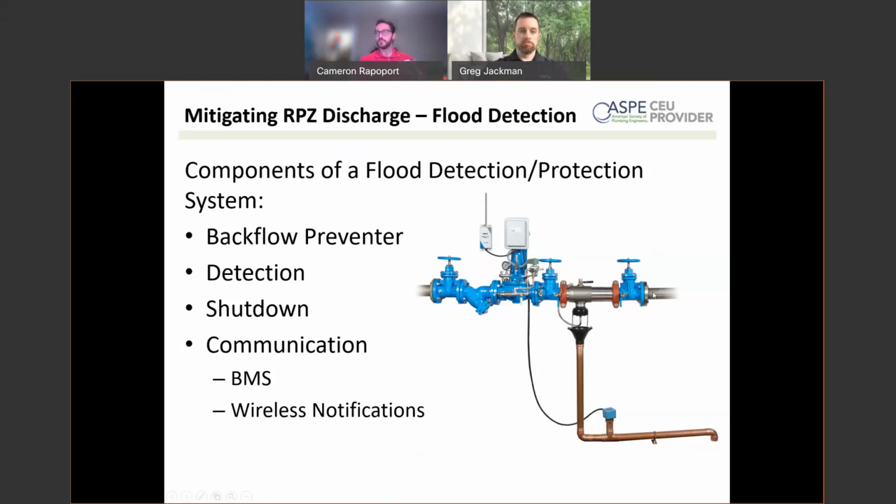The other one that you mainly see is something that actually monitors the relief valve stem position. It'll detect when that relief valve is open by where that stem is as it moves back and forth with that diaphragm. These are a great option to have. Customers, even contractors, often do not realize just how much water can come out of these things.